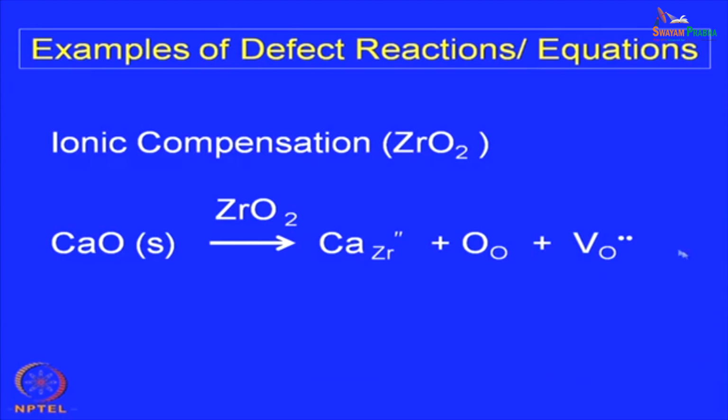So, you remove some oxygen; some oxygen ions are completely removed. Here there is no change of valency, because all these ions are very stable valent ions, whether it is oxygen, zirconium, or calcium. Zirconium valency change is very difficult, it is energetically not possible. Calcium is also the same thing. So, what can happen is that some of the ions are removed from the lattice. That is what happens: an oxygen vacancy is created, oxygen goes out.